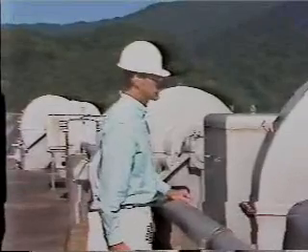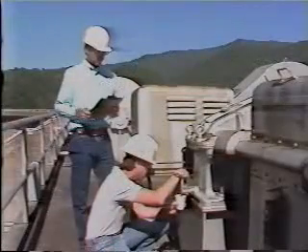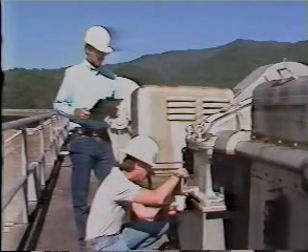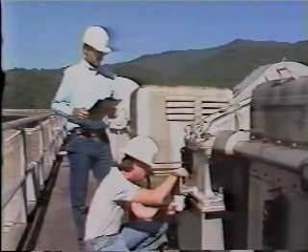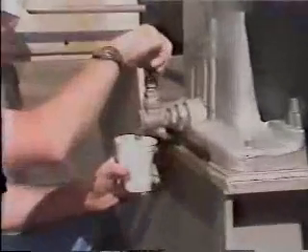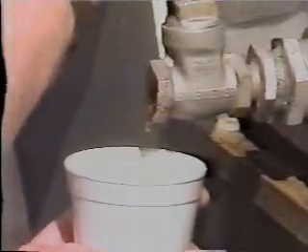When you're inspecting the hoist, look for condensation in the gearbox and oil sump. Drain any water in the oil sump and record the amount. It's important to do this before the gate is operated so that you can identify the condensation. Otherwise, the action of the gears will mix the water with the oil in the sump and you won't see it. Next, check that all the labels on the control panel are correct.